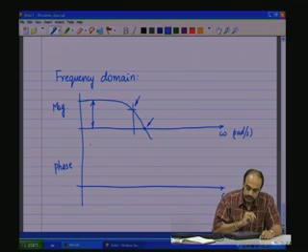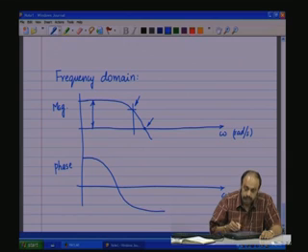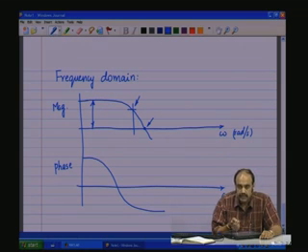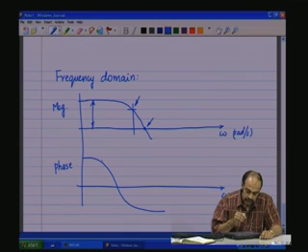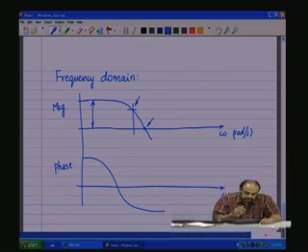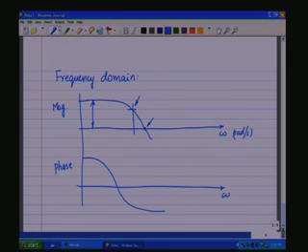So, corresponding to those frequencies, what will be the phase plot and how does it look like at various frequencies? Is it going to be in phase, or is it going to be having no phase shift with respect to the input waveform? Is the response having 90 degrees phase shift, 180 degrees phase shift with respect to the input waveform? These are issues that you can obtain. These are the information that you can obtain from the frequency domain plots.